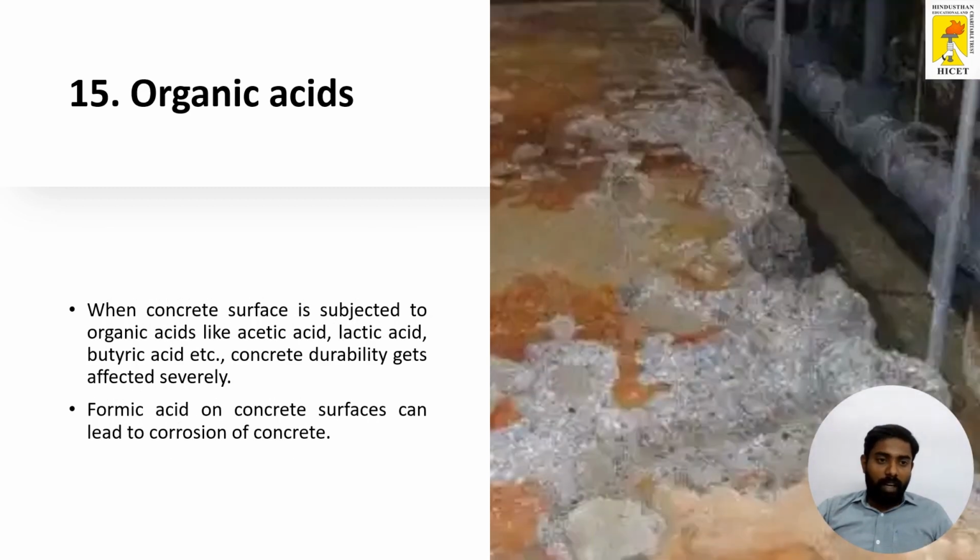Next one is organic acid. When the concrete surface is subjected to organic acids like acetic acid, lactic acid, butyric acid, etc., the concrete durability gets affected severely. Formic acid on the concrete surface can lead to corrosion of the concrete. These are the various factors that affect the concrete's durability, that is, the lifespan of the concrete.